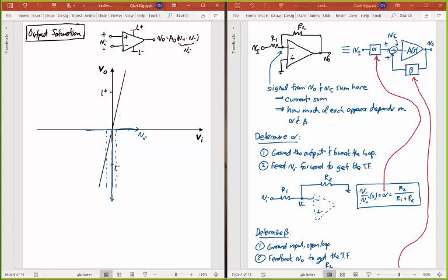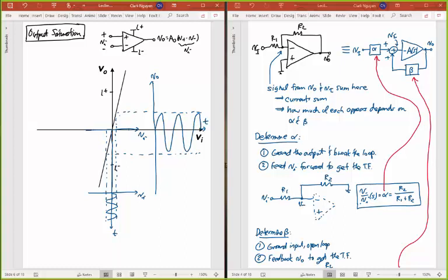Well, let me draw the sinusoid down here so it doesn't disturb that curve. Let me pull this out a little further. That's time. And let me make my VI axis here instead. So that means I'm putting in a sinusoid that looks like this between that. And if I do that, then I project it up to this curve. You know already, because I've done this before, that I can do this. And if this is now my output voltage, let me make that much bigger here. If this is my V out, and I'm creating a time axis here, then I've taken this tiny input signal and I made it bigger. And so you can sort of see how this amplification occurs just because I've got a large slope, gain slope right here. So this slope is that gain A0. Okay?